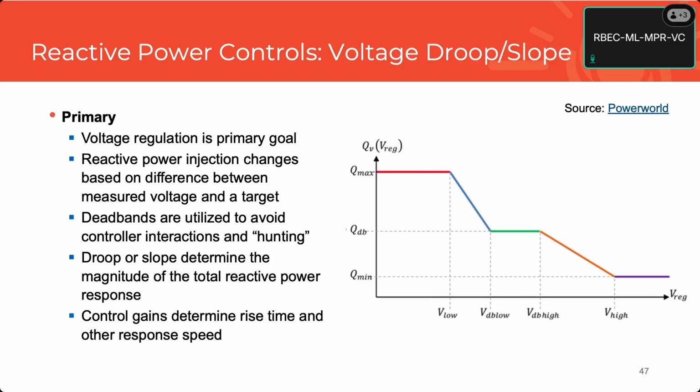The other thing to note here is similar to frequency ramps. If you have a really complex IBR, you may have 3 different ramp rates or 3 different slopes in here. And it's really important to make sure that when you're asking for it, when you're providing it to someone, that you're all on the same playing field, right? The utility wants one slope, maybe, with one level. They may not want 5 different slopes to get there, but you may have that in there. So just another one of those places where it's really important to keep your language consistent.